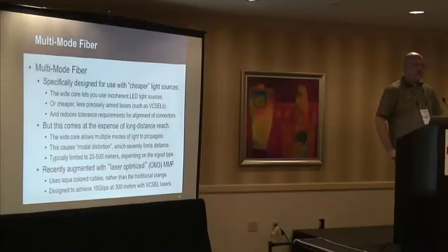What happens is you get multiple modes of light in the fiber, and you get distortion. So I'll talk about that in a minute. But basically, you're looking at distances anywhere between 20 to at max 500 meters, depending on the type of signal and the exact type of fiber. There's also recently a laser optimized multimode, which uses aqua-colored cables, and that's designed to let you do 10 gigs up to 300 meters. Before you had that, you might do 10 gigs on multimode to 20 meters or something along those lines.